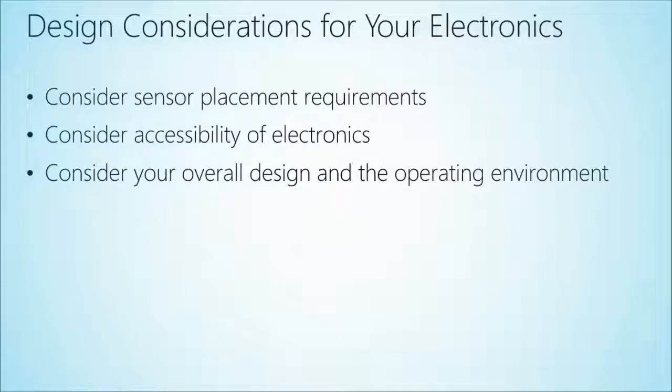your sensors. So they're reading something. These are your inputs, right? And some of the sensors are going to be line of sight sensors. So they're going to need a clear view. You might be positioning them, rotating them, right? As for our MS GuardBot robot, we move the rangefinders. We position them 180 degrees, right, in different directions. So they need a clear line of sight as they move. So they have to be positioned appropriately for that.